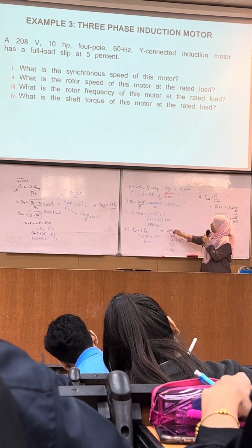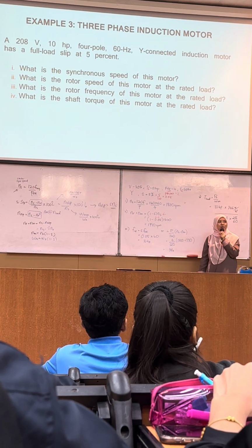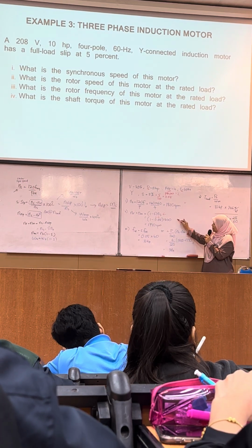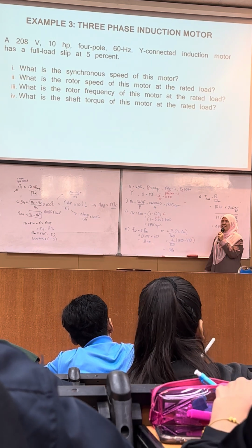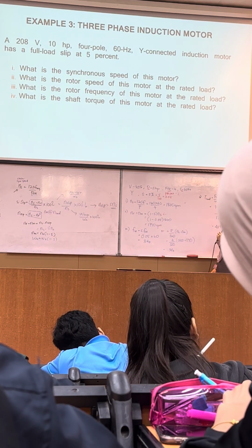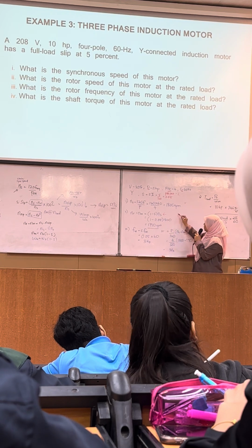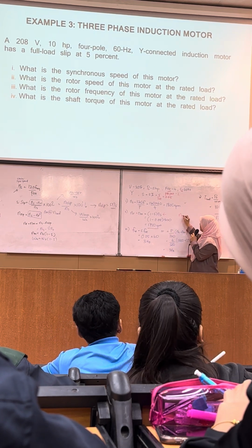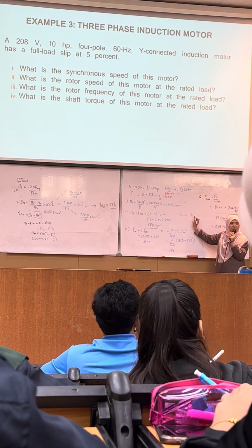Frequent mistake, you akan letak 5 di sini. 0.5 di sini. So, salah. Salah ke atas, yang bawah semua dapat separuh. That's how you lose your mark. Okay? So, it's 0.05. Then, you will have your motor speed. So, now, you can verify that rotor speed will be always lower than stator speed ataupun synchronous speed.